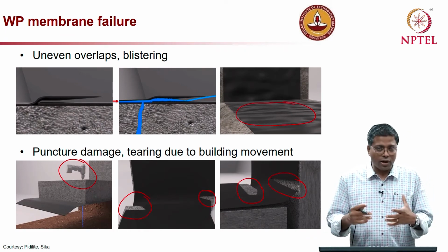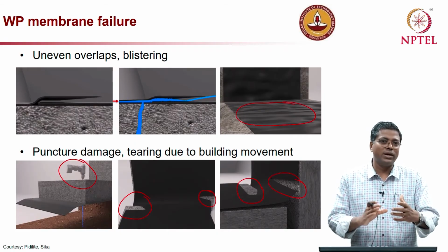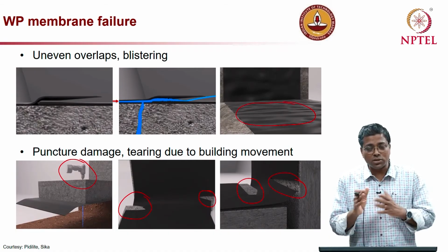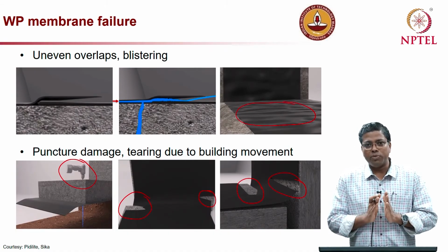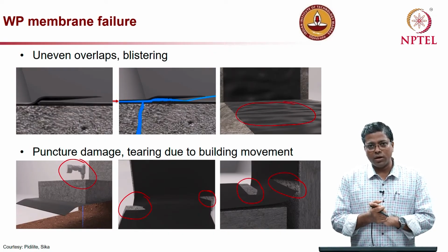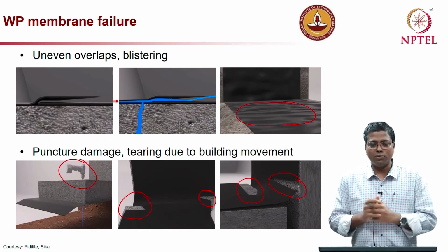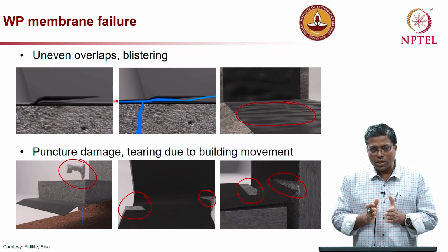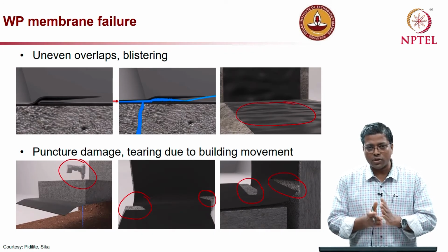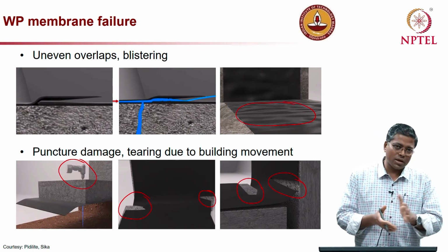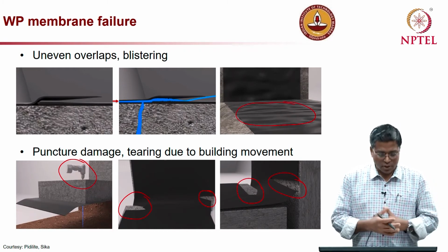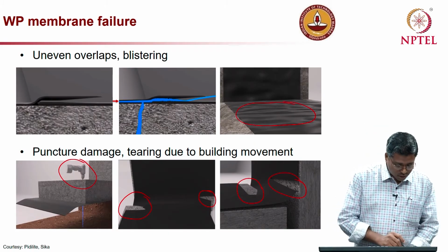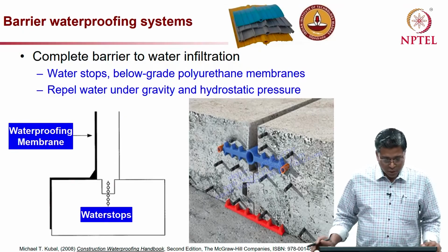Because if you want very high elongation, only provide it where it is required. So, the engineer at site has to decide that if there is a joint and there is a possibility of significant movements, let me put a material which will have very good elongation only in that region, because as you ask for this kind of material, the cost is also going to go high. So, you can use materials with high elongation only for the joints, and the remaining regions can be with some other material, and then provide a proper joint glue between the two systems.